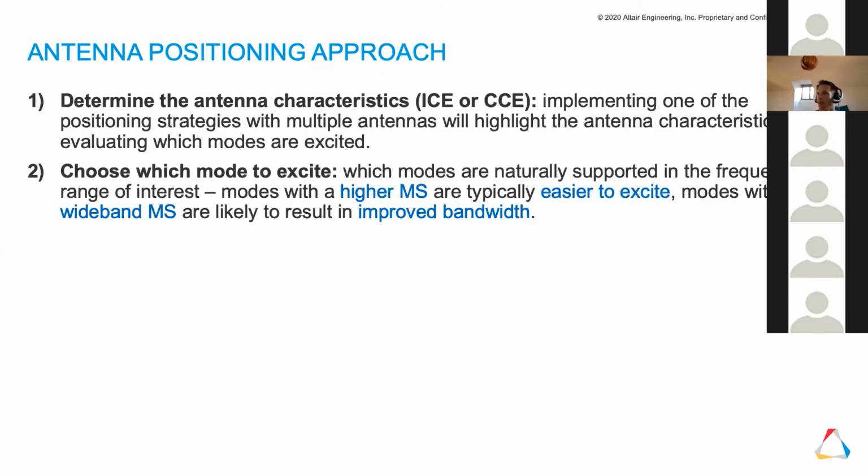The next step would be to decide which modes to excite. There are probably 2 points to mention here. Typically, you may say it is easier to excite modes with a higher modal significance. But in the context of this work, where bandwidth is our criterion, it's also worth looking at the bandwidth properties of the modal significance. In other words, it may be beneficial to excite a mode that has wider band properties rather than a mode that has a higher modal significance.